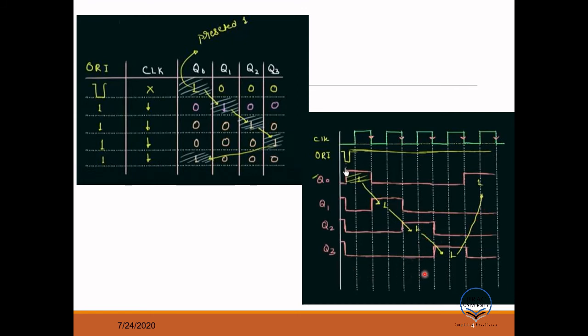So for this one again, it will change state at the clock edge here. So 0 becomes 1. And at the next clock edge it will change state, and for input 0, output will be 0. Okay, so if you look here, 1 1 1 1 1. So it's creating a clock. That's why the ring counter is forming a ring kind of structure.